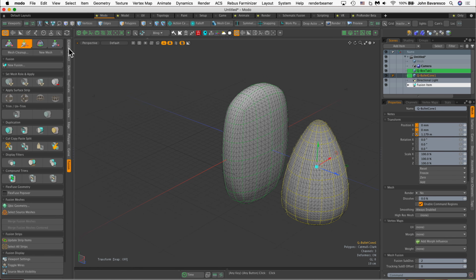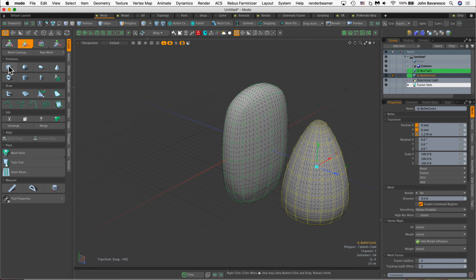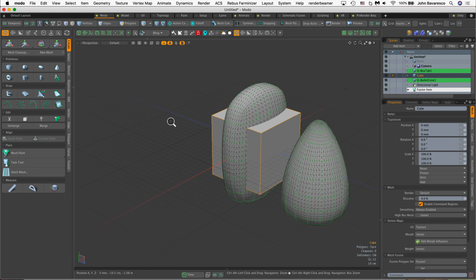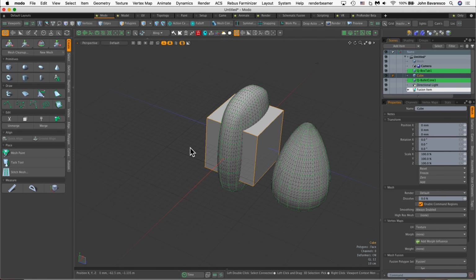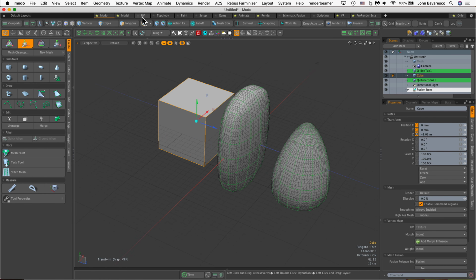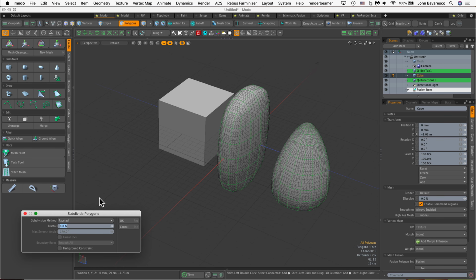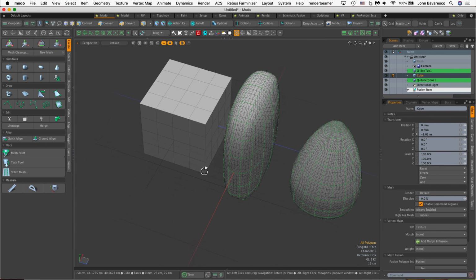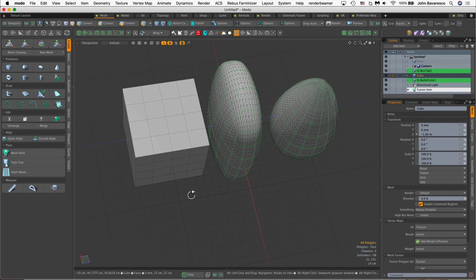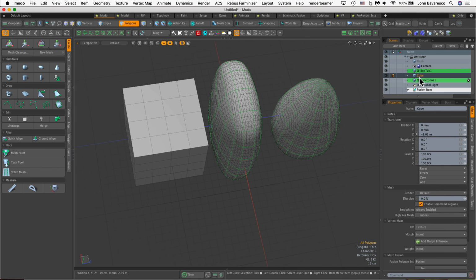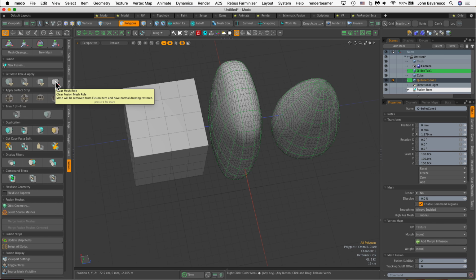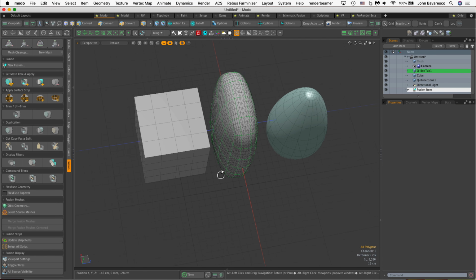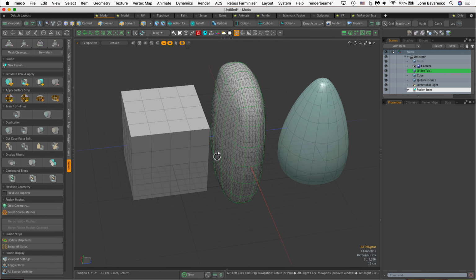I'm going to go ahead and add just a cube to a new layer there, and I'm just going to move it off to one side. And in component mode, I'm going to just divide this, and maybe one more time. Okay, so there's my cube. Now I'm going to make this cube intersect with my main object. And just for the sake of simplicity, let me go ahead and undo the fuse on this one, just so that we have one thing going at a time here.